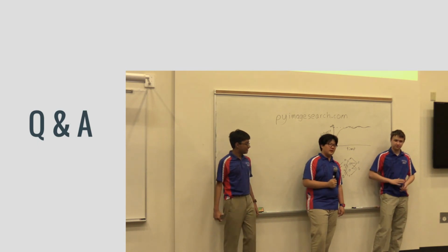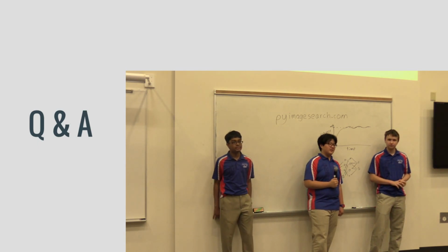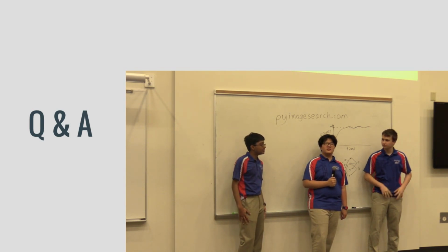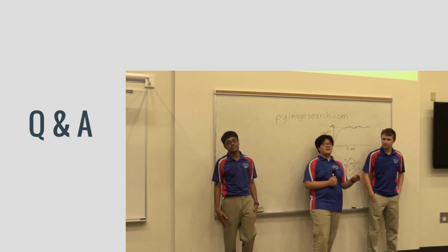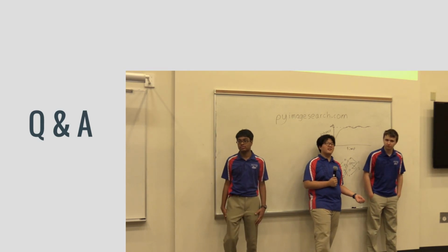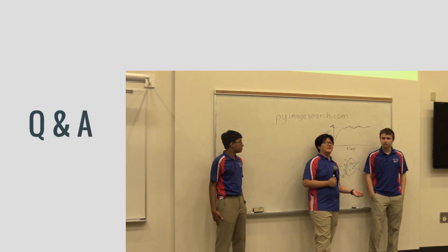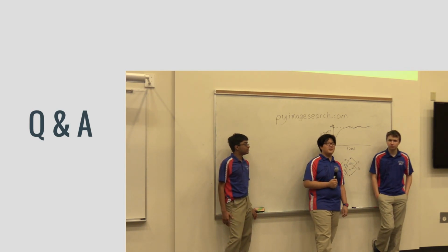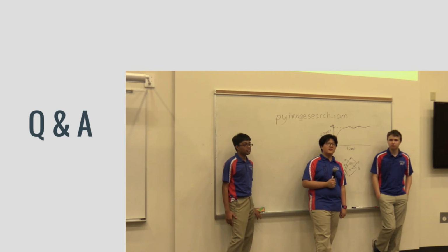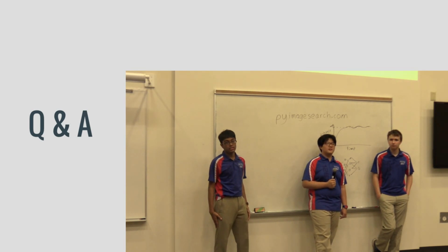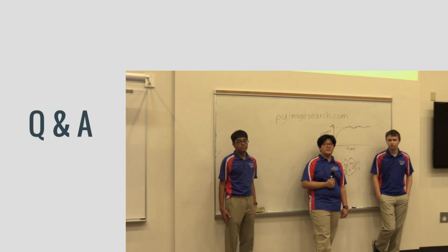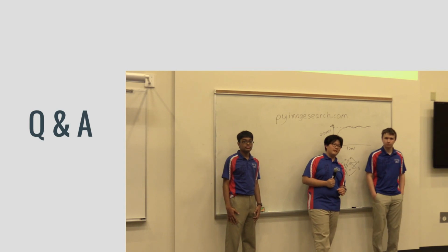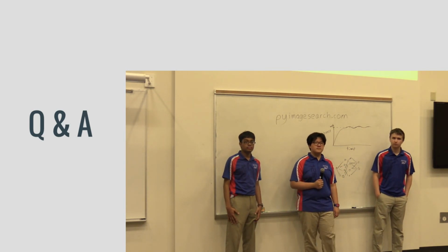Another interesting thing about the Pi 3 though is that it's the first Pi that actually heats up significantly. The actual chip heats up to about 100 degrees Celsius, which is supposed to be the limit. It starts throttling at about 80 degrees. So I really recommend that if you're using a Pi 3 and doing some intense stuff on there, you put a small heat sink on it. It'll improve it quite a bit. If you put a full CPU heatsink, I think you can improve performance by 50% or something ridiculous. But yeah.